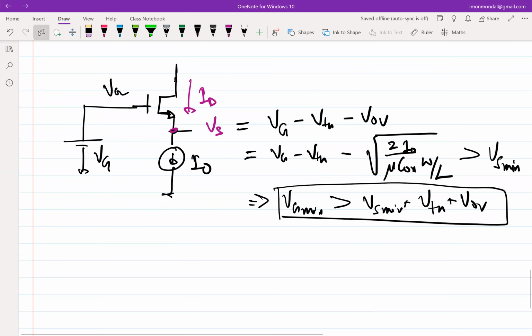I have not even shown what is at the drain. As far as biasing is concerned, does it matter if I connect the drain directly to the supply? It doesn't really matter, it's already biased, as long as the supply is greater than one threshold voltage above it. So it should not be a problem. Now, as you pointed out, I need to figure out how to apply an input and take the output. So let's apply an input.